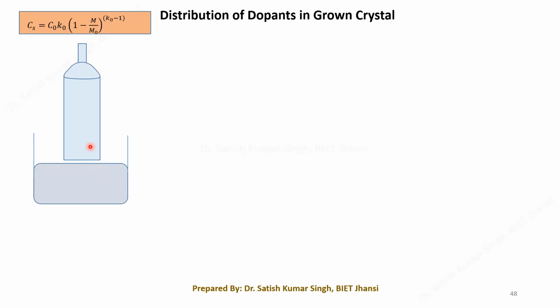So what we are saying is 30% of this dopant is being rejected. When it is rejected, it will be available at the surface. You can understand that where it is touching the surface, slowly or progressively the upper layer of this melt will become progressively concentrated, meaning the dopant concentration is increasing. Progressively, the dopant concentration at the top surface of the melt will start increasing.